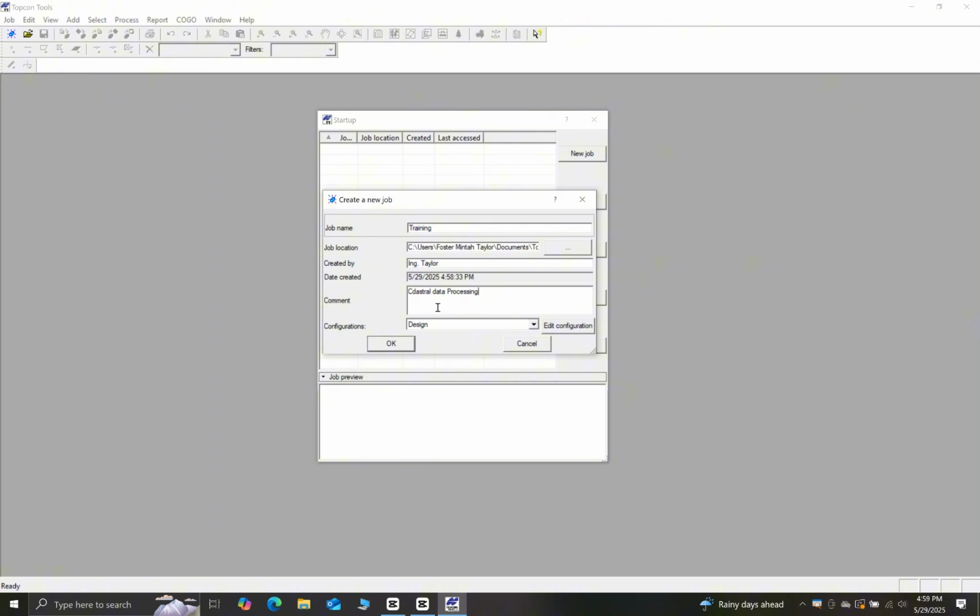Now the very important area is this part. Before we process any static GNSS data, we need to make sure that we set the data and the interface to the correct coordinate system, which is the Ghana National Grid, also known as the War Office system.